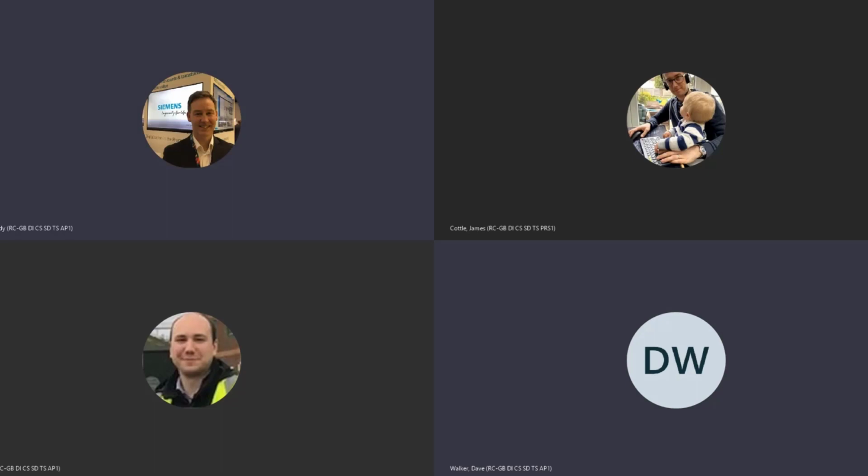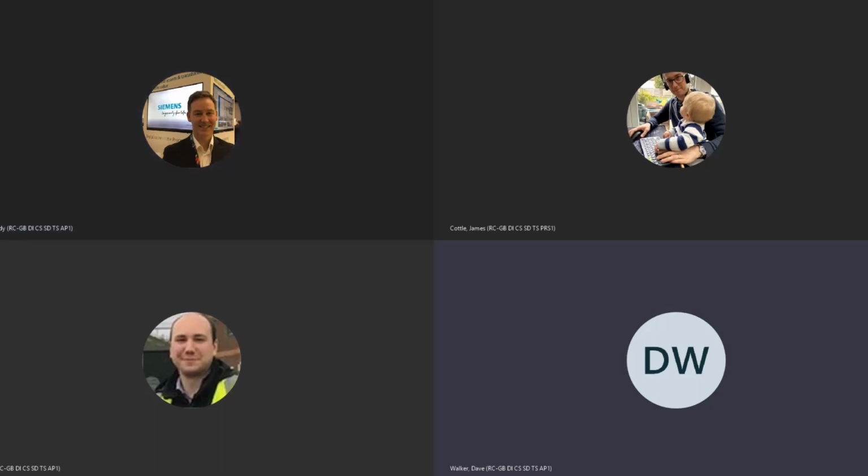Thanks, Andy. The important thing to set up the integrated diagnostics is to create a connection between the PLC and the HMI. So when you're creating connections in your networking devices and networking tab, just simply go on to connections. Everything that can be connected together has now gone this cyan blue. Any connections that are pre-built, if you just highlight them, you can see that we have a connection between the HMI and that PLC. But also a really nice feature with an integrated PLC and an integrated display is that we can use routed connections.